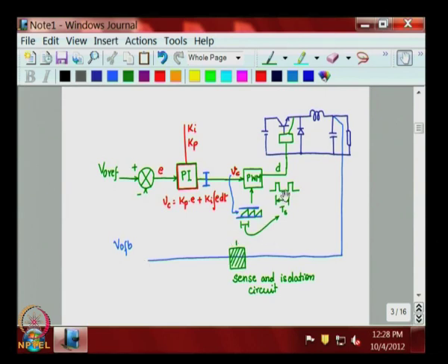If it is not okay, if an increase here is resulting in a decrease here, you will have to change the phase relationship in any of these component blocks. In the PWM, the output of the PWM can give you plus or minus 180 degrees phase change by choosing the output across the collector or the emitter point of the PWM IC. That is one possible point. There would be op amps in the PI, where you could possibly have 180 degree phase shift achieved, and also in the op amp at this compare point.